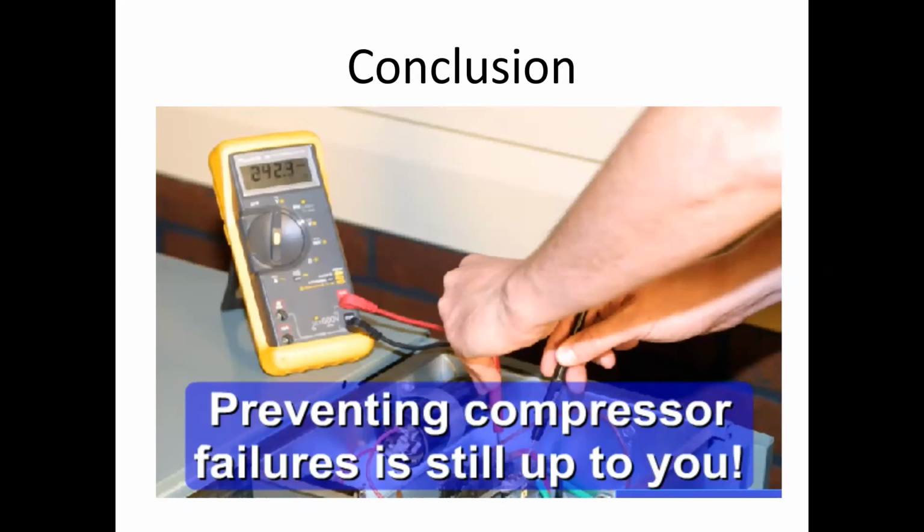How do we prevent compressor failures? By making sure that we've got proper airflow, we've got proper refrigerant line sizing, we've got proper charge, and that our high and low voltage wiring is good, and that our voltage is in spec.